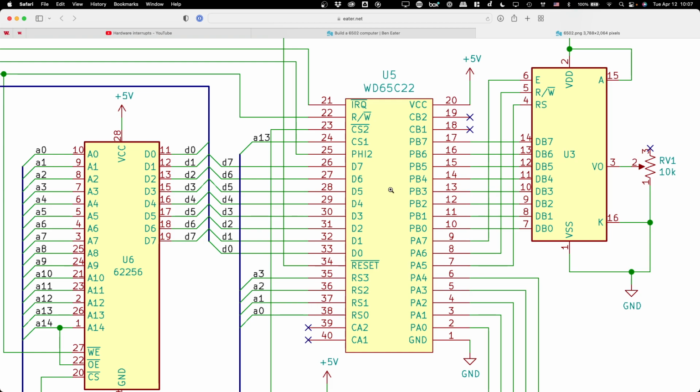When an interrupt gets triggered, we'll figure out what caused it, and before we stop servicing that interrupt, we'll say, okay, got the interrupt, clear the interrupt line so it goes back high.